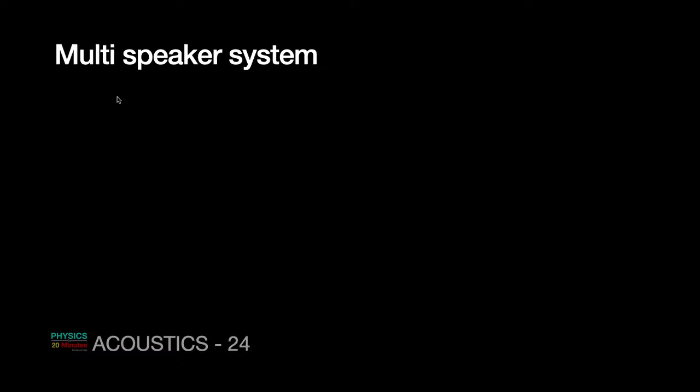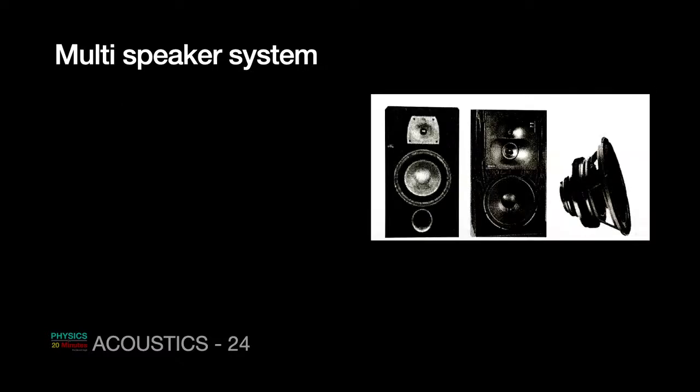Practically, if the speaker is small in size, it might be achievable. For example, headphones and earphone speakers do achieve the entire spectrum range because the volume of air to be moved is very small. However, if you are going to a large room, a big speaker, if you want larger volumes, then a single speaker delivering the entire frequency spectrum is not feasible. So we require a multi-speaker system. Today we will talk about the basics of multi-speaker systems. So this is how they look.